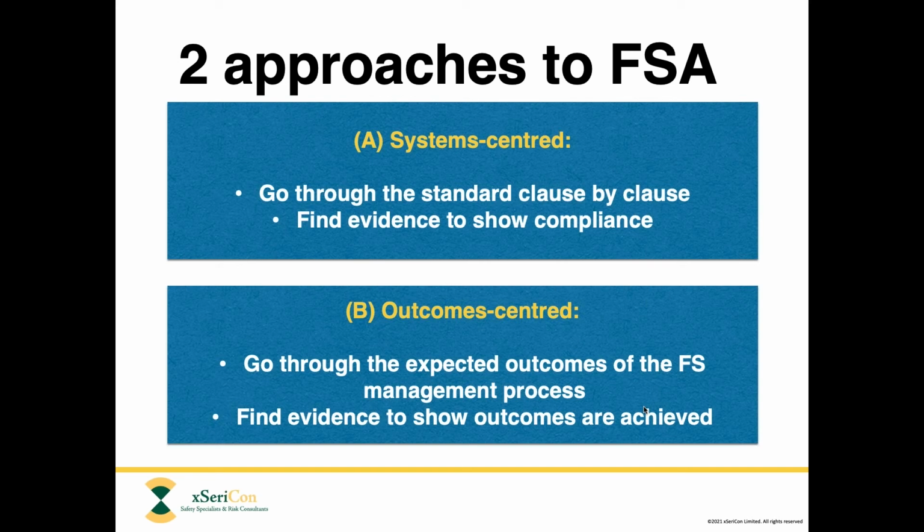The first one is what you might call a systems-centered approach. This is where you typically go through the relevant standard, for example, IEC 61511, clause by clause for every single relevant clause, relevant to the stage that you're performing the FSA for. And you search for evidence to confirm that each clause is being complied with. So it's very much going through, ticking boxes one by one, focused on compliance with the standard. The second approach is what I would call outcomes centered.